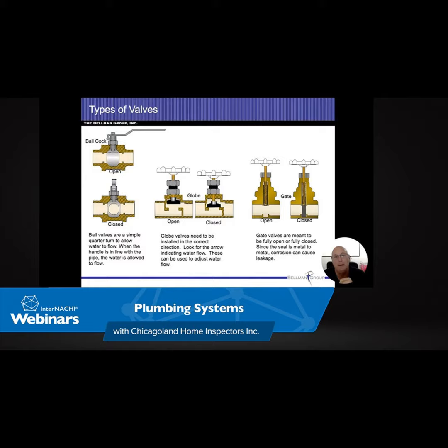Shallow wells are typically going to be, if you've ever been to the forest preserve and they have those wells that you're going to pump up, those are shallow wells. You're typically going to have a surface pump that's going to create a draft and siphon that water out of the well in order to make it work. Very rarely are they going to be lined in any which way. They may have a stone liner, but they're going to be gapped and open, and the water table is just going to be that high that we're going to get water out of it.